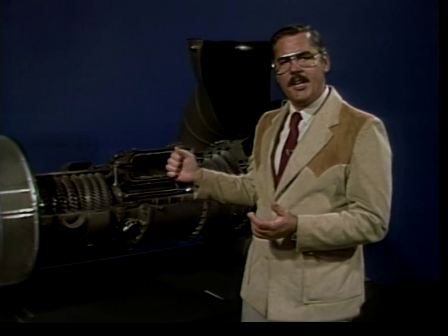The question you may be asking yourself is, how does air movement get changed into pressure? The answer is related to the shape of each compressor blade. Each blade is shaped like an airplane wing or airfoil. Air flowing over the top of the airfoil must travel over a longer path in the same length of time it takes the air to pass across the bottom of the airfoil.